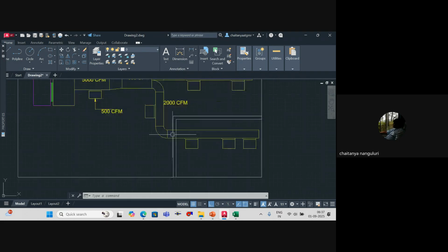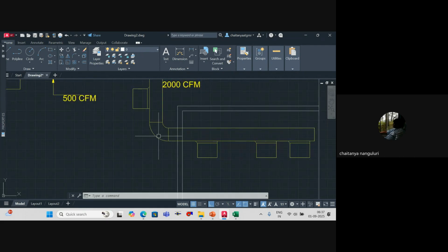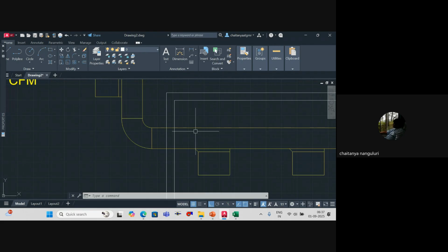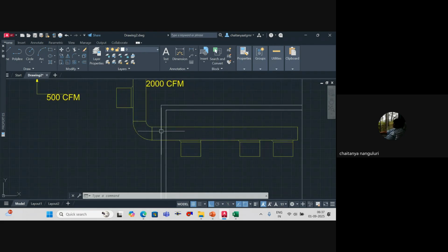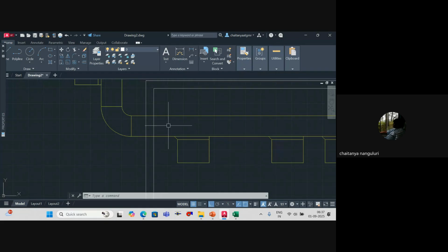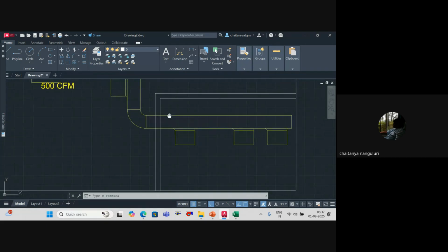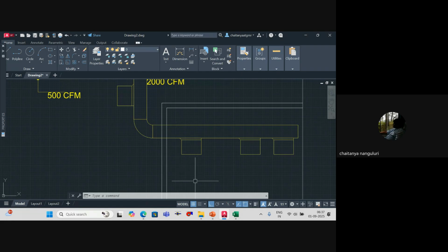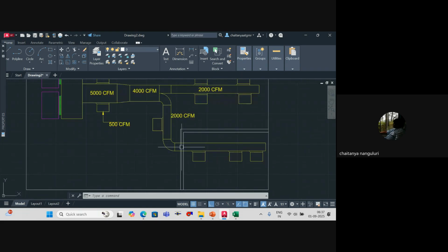But the weakest spot, don't you think, is your ducting? Because you have used ducting according to your width, say probably 24 gauge. But can you guarantee that the duct can withstand fire? Obviously not. If there is a fire, it can easily melt away the duct, and that will result in the smoke or the fire going through this opening above the ceiling, through this duct. Or if there's no ceiling, through the opening in the wall. You agree? If there's a fire here, it can cut the duct, or even the smoke can escape through this.